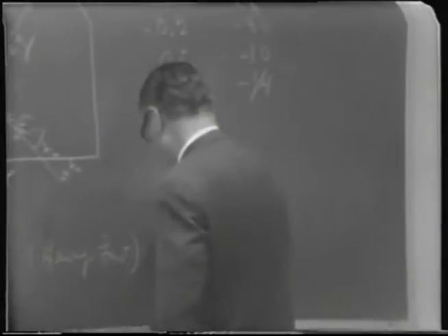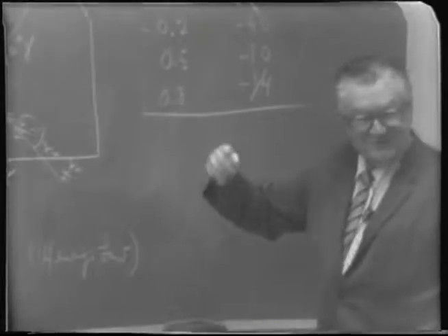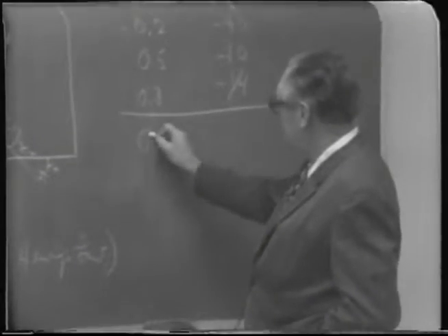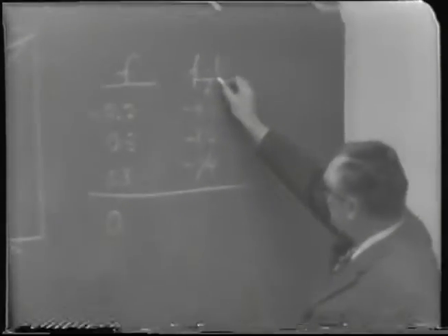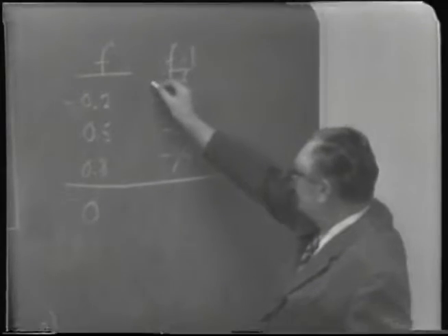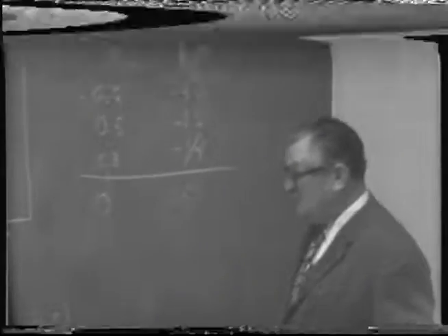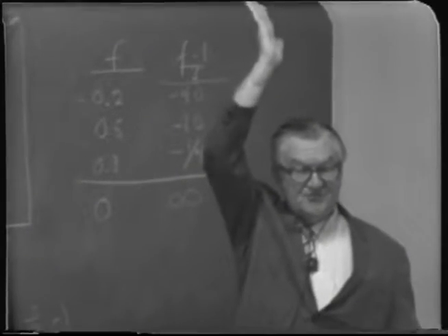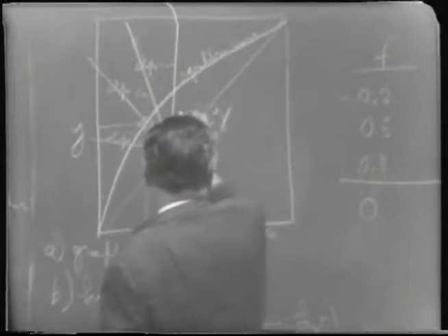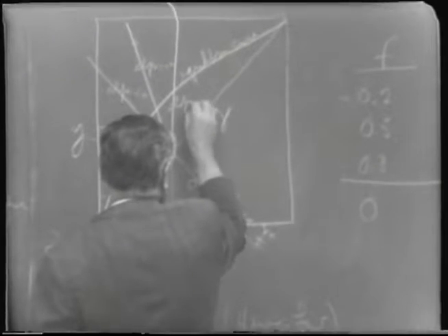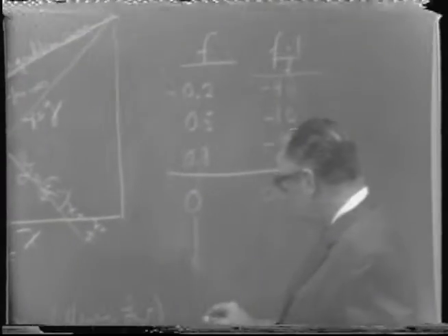I'll continue this little table here, which is the way you'd start out working this problem. If you have 0 as the fraction vaporized, what would this value here be? It'd be -1 divided by 0, which would be infinity, wouldn't it? So the slope of the operating line would be infinite. It'd be a vertical line. So that right there would represent the operating line when the slope is infinite. And so you can continue on down through here until you get to 1.